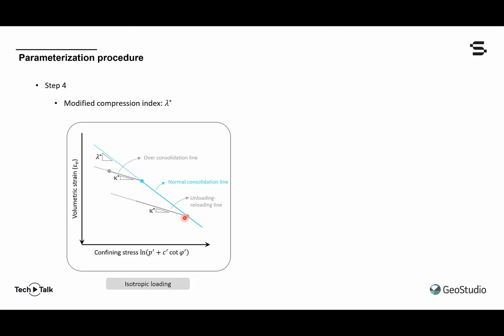In other words, if we had taken that previous example that I just walked through, let's say that the specimen was isotropically compressed along the overconsolidation line, and then it yields in isotropic compression, and we track along the normal compression line. Hence, it is often referred to as the isotropic normal compression line and designated ISO-NCL.